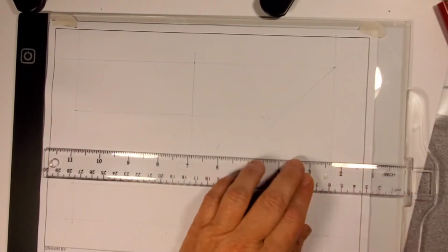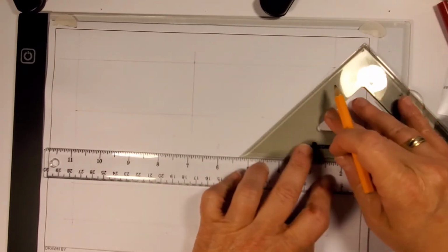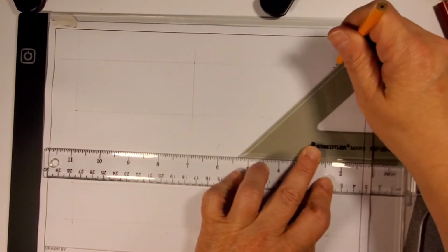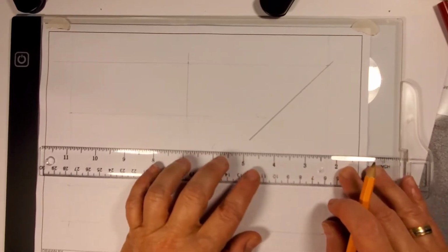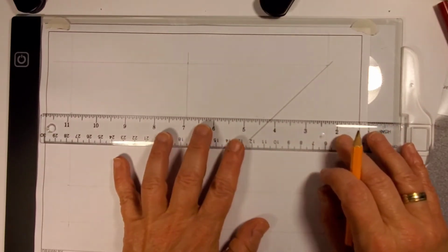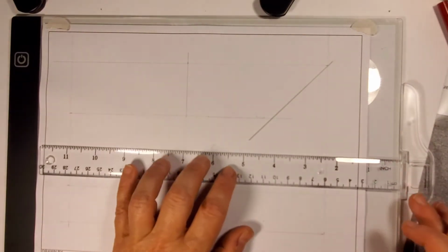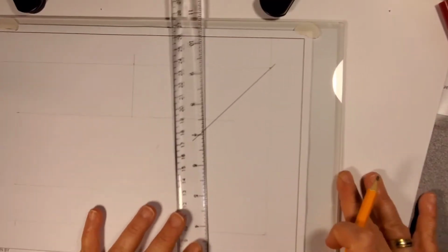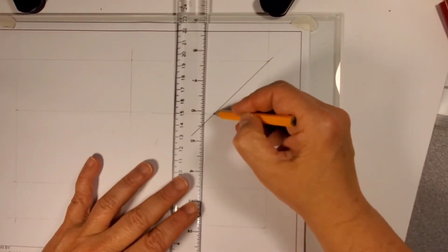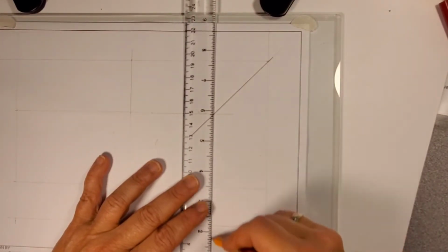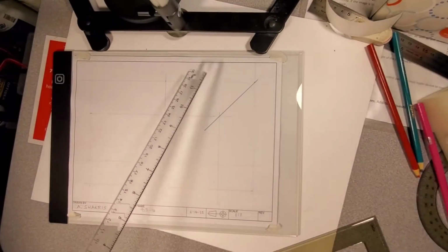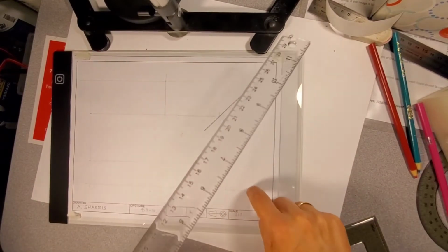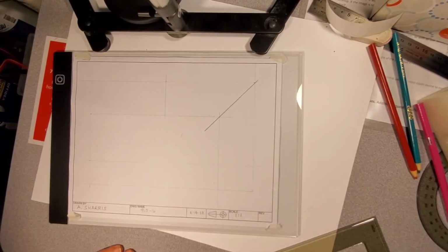See that line? This I'm going to make darker for the purpose of the lecture. On your actual piece of paper, I want you to not make it this dark, because at the end you want to erase it. Got it? So you can carry your line across and then straight down, and start your bottom view. See? Your right side view here, just by carrying those objects across.